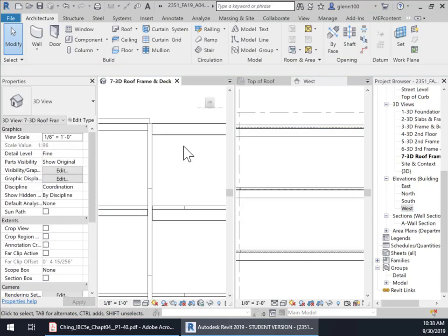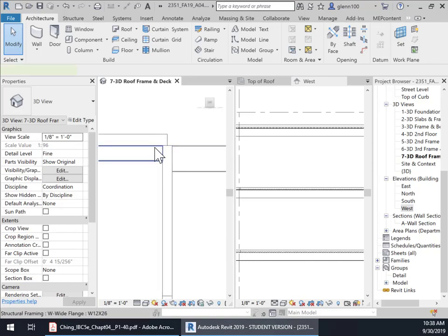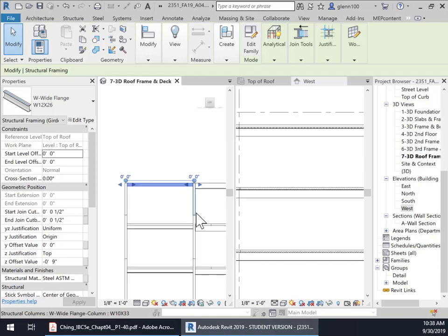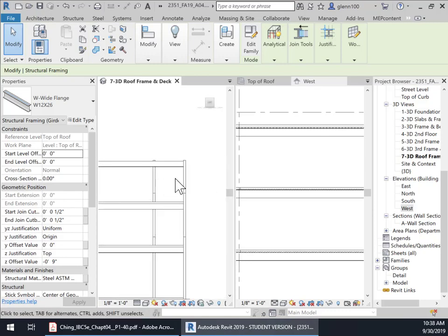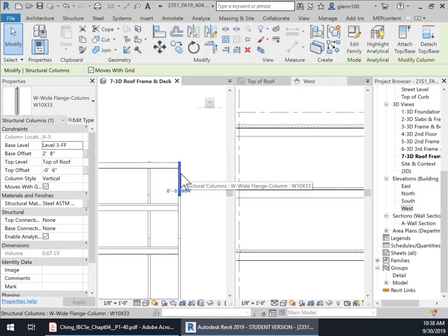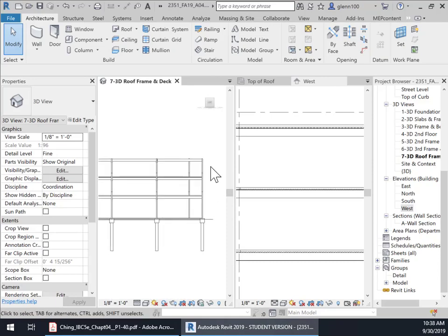And that's going to drop all those beams down where they should be, and that is even with the beams that I originally made that are in the file. Okay. And then you'll notice that all my columns now are the wrong height. And so they need to drop down to 9 inches instead of 6 inches too.